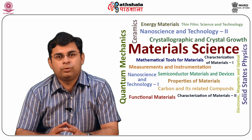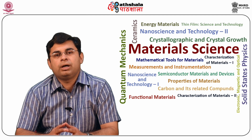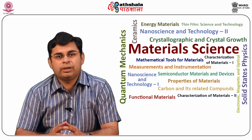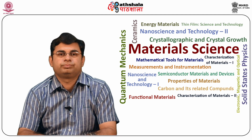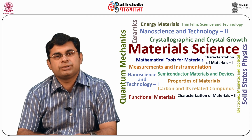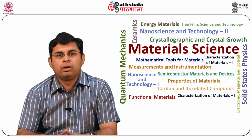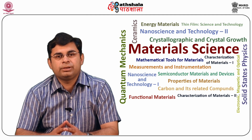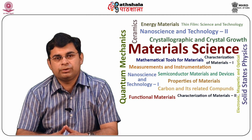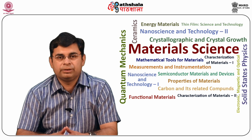It is important to note that this bridge does not require equal values of R and C. In one arm, we have an RC combination in series, and in the adjacent arm, it is a parallel combination. This bridge is designed to measure frequency and is used for measuring a capacitor with great accuracy. In the arm in which the capacitor is in parallel to the variable resistor R3, admittance value is used rather than impedance.